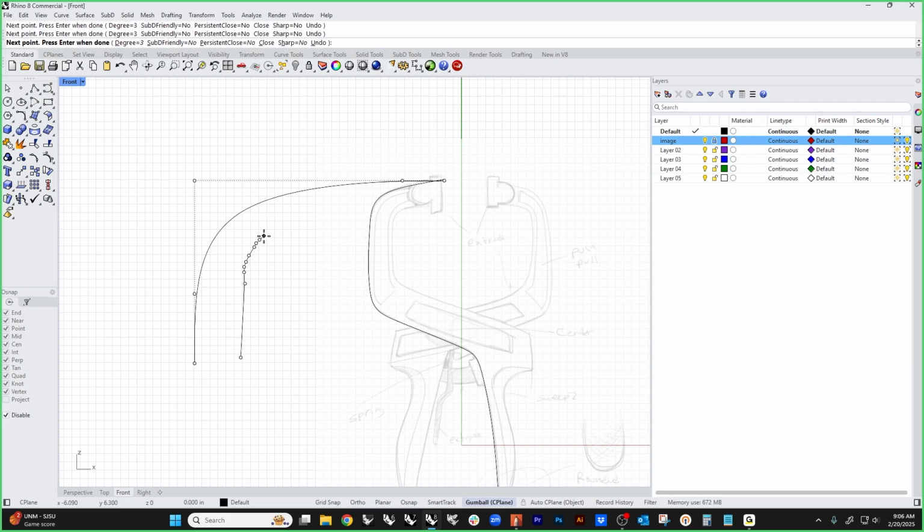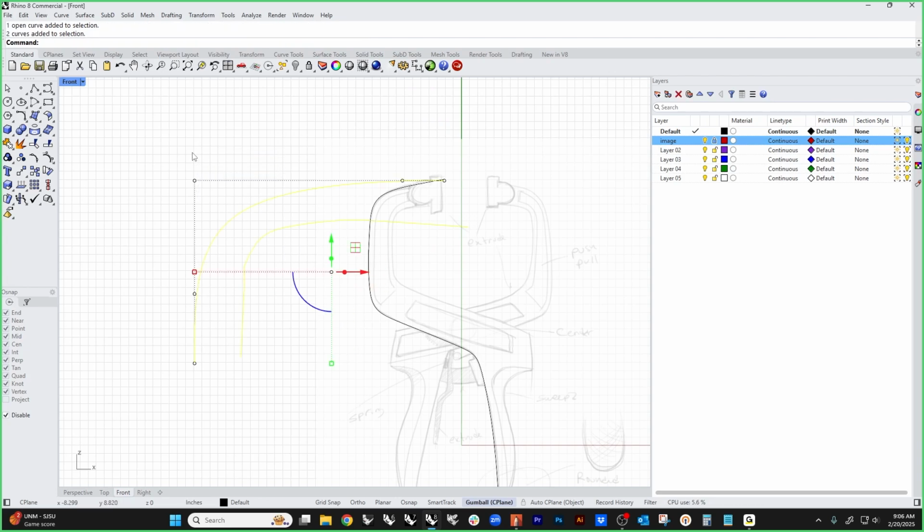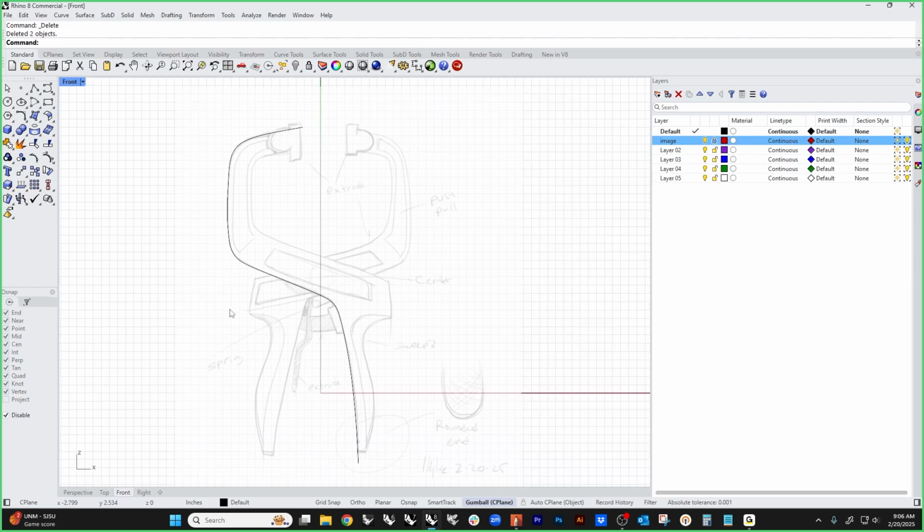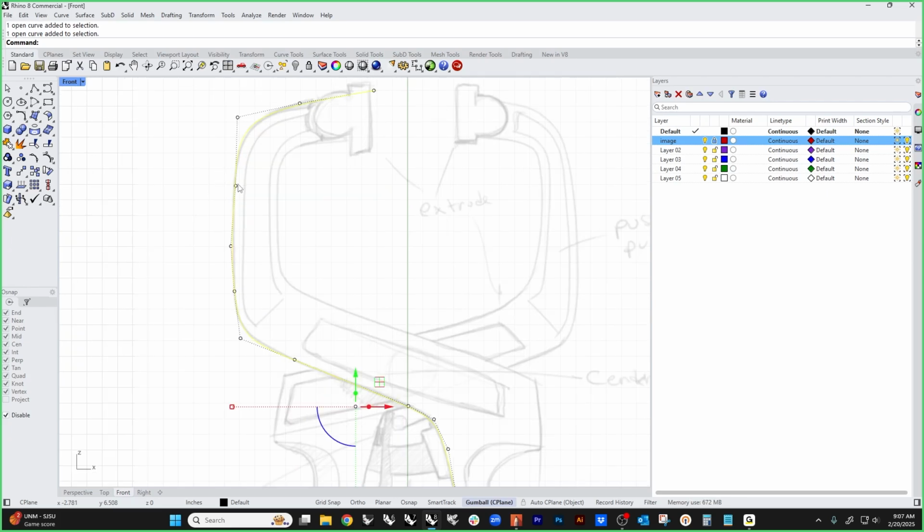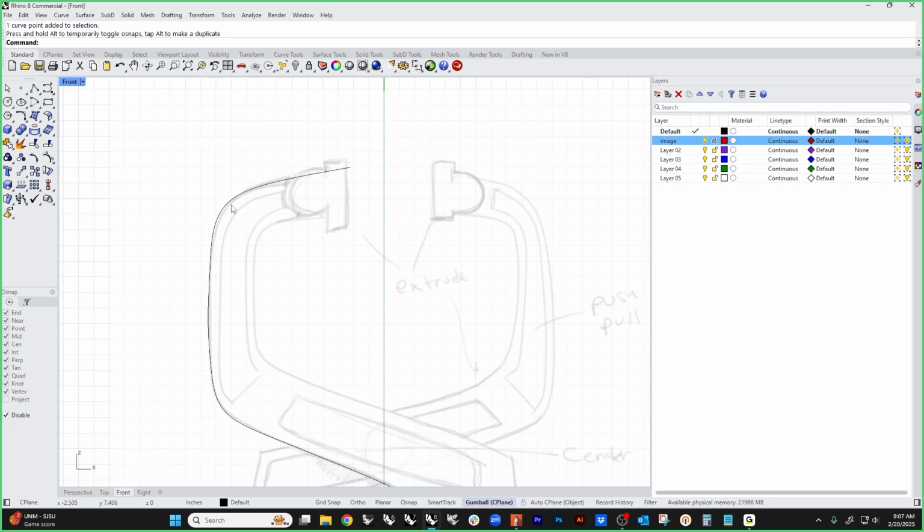Don't do that. This makes everyone sad, especially you, because you're going to have to deal with the surface that makes later. So we're going to make nice, simple curves. We're going to use 3 points for each section of the curve that has a transition in it. And we're going to be fussy little designers, and we're going to tweak that just a little bit with nudge